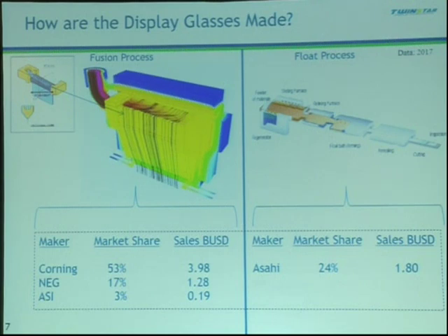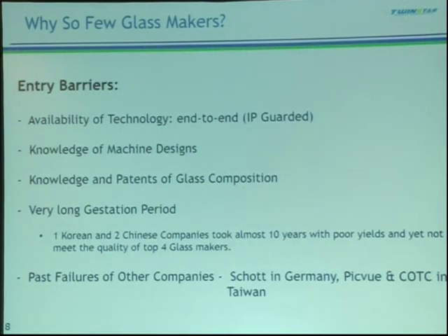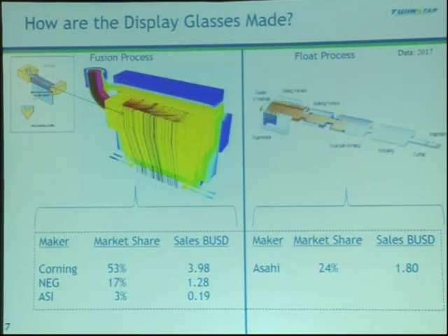Corning has come up with the state-of-the-art forming process, which is the fusion process. In the fusion process, you use an isopipe, and the glass flows in. Isopipe means the same hydraulic flow rate, which means the glass flows out of the pipe equally in volume when it goes down. So the glass is extremely flat, and when the glass comes down from both sides, it meets at the root and fuses at that point, and that is why it is called a fusion process.